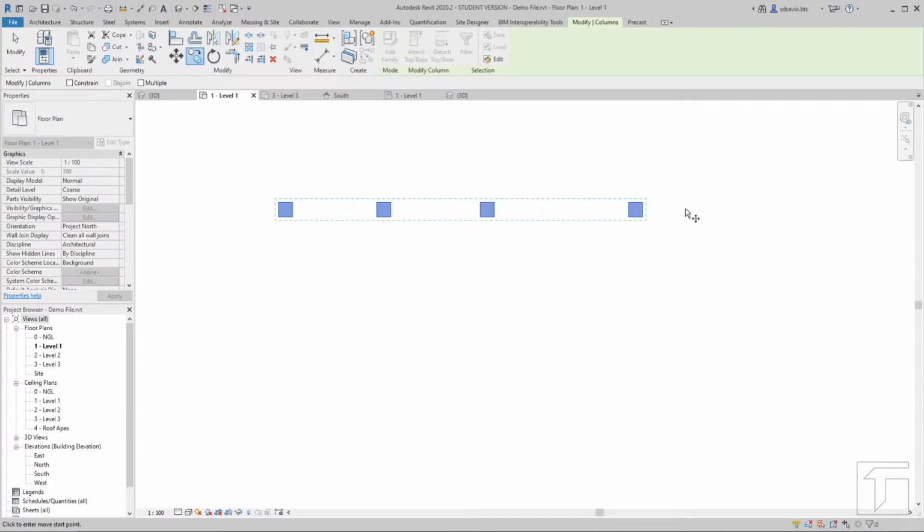Actually, you can click anywhere. Again, I'm roughing in the column, so I'm not so strict right now with the dimensioning or the distance between the upper columns and the lower columns that we'll be copying. So let me copy that. I'll click anywhere on the screen, and then I will move my mouse downward. Notice that there's a temporary dimension that follows my mouse cursor, and it tells me the distance. As I move my mouse downward, the distance increases, telling me that from this hidden guide that has appeared, it is 1,700 millimeters from the origin.